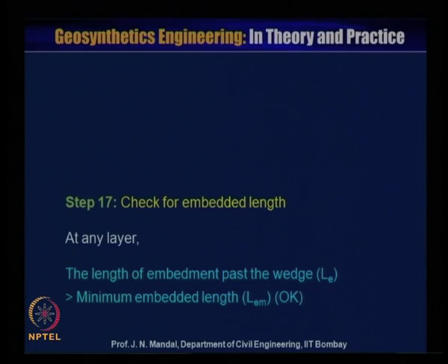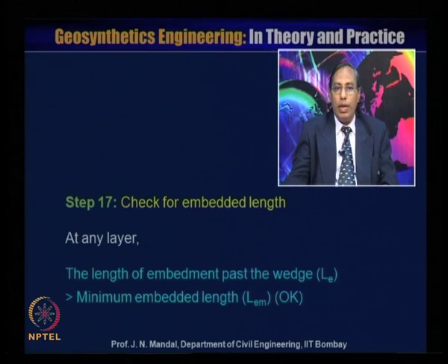Step 17, check for embedment length. At any layer, the length of the embedment past the wedge is LE. It should be at least the minimum embedment length LEM, then it is okay. So you have to check.